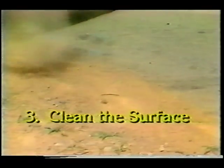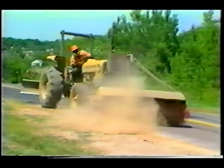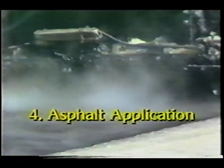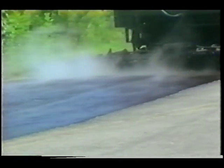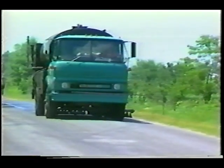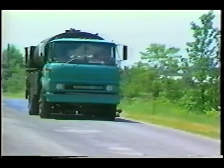Step 3, clean the surface. Remove all loose material from the pavement surface prior to the seal application. A tractor-mounted broom is effective in removing most loose debris from the pavement surface. Step 4, asphalt application. The asphalt application is the most important part of a chip seal operation. Emulsified asphalt is recommended. The asphalt distributor is set up for the proper application rate. Monitor the application for proper application rate to prevent streaking.